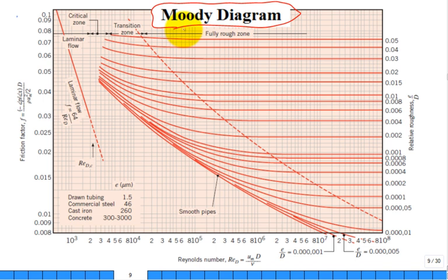All right, so what's on the x-axis of the Moody diagram? Reynolds number. Is it a linear or log scale? Log. You're covering a lot of terrain. And so way down here is what's at 1,000. Hey, we're below 2,000. We're in the laminar region. But you know what? That's the whole laminar region. What's above? A whole lot of real estate devoted to turbulent flow. All right. What's on the y-axis?